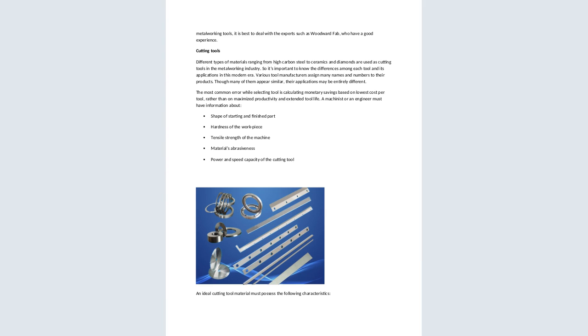Various tool manufacturers assign many names and numbers to the products. Though many of them appear similar, the applications may be entirely different. The most common error while selecting tools is calculating monetary savings based on the lowest cost per tool rather than on maximum productivity and extended tool life.